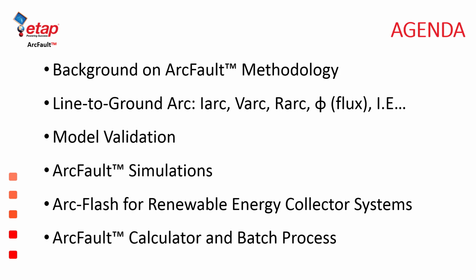We will also discuss through the presentation how ArcFault was designed to help engineers provide reasonable yet conservative estimates for arc flash events in enclosed equipment between 15 to 36 kV. Last, we will introduce the ArcFault calculator, which is a very powerful tool, which is part of the ETAP 18.1 release, which will follow our current ETAP 18 release, and we will discuss how this powerful calculator can be used to interface with even third-party databases.